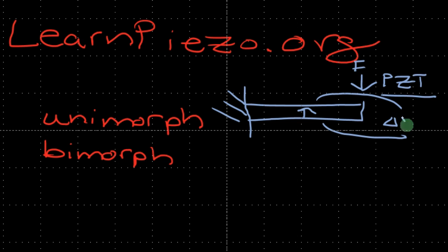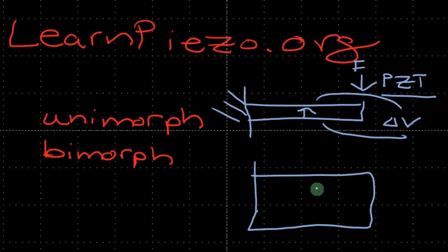So what's the difference in potential if we apply force there? Because there's tension and compression, as we know. If we split it up and show the stresses occurring, if we push it this way, there'll be compressive stress, which I'll draw in this direction, and there's going to be tensile stress on the top. So tensile on the top, compressive on the bottom.